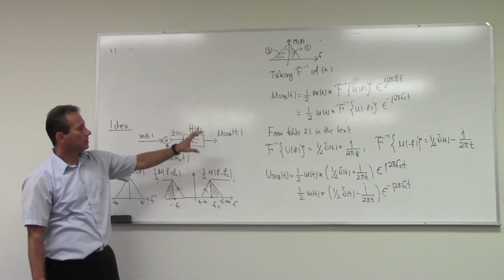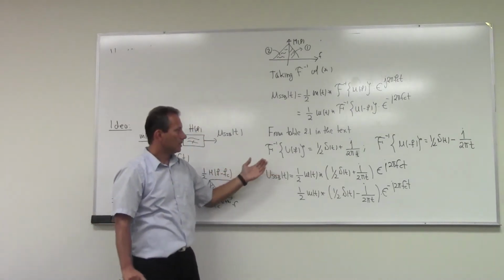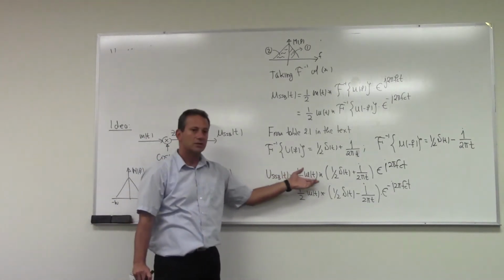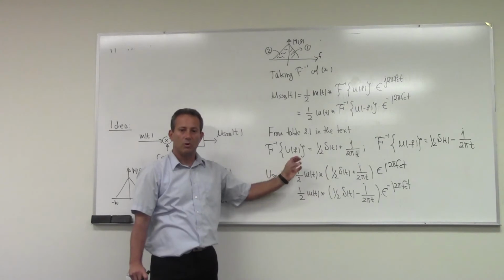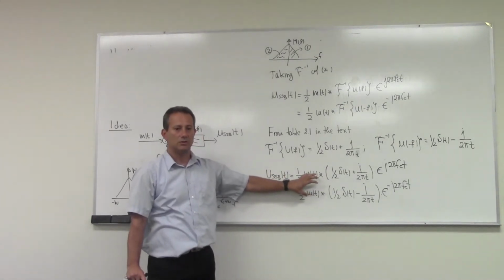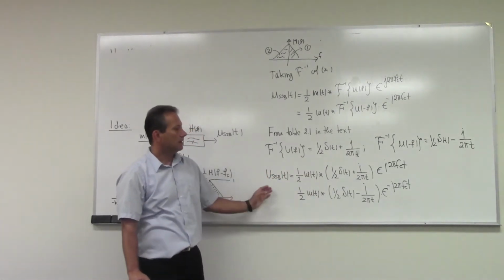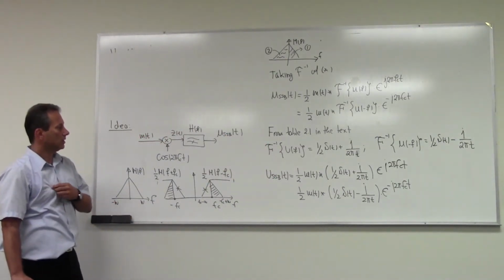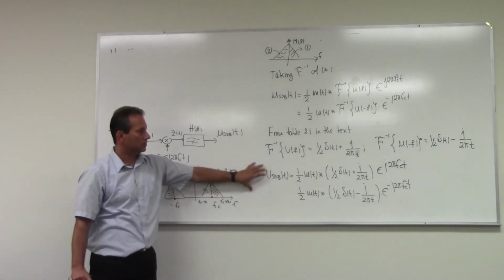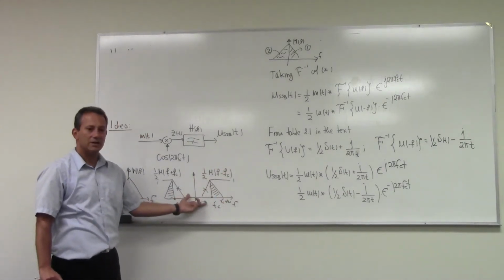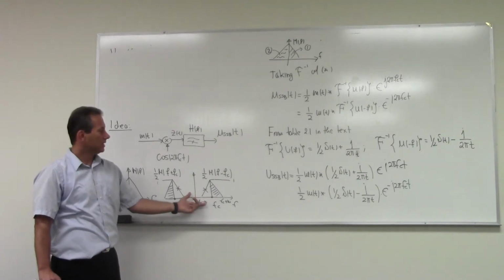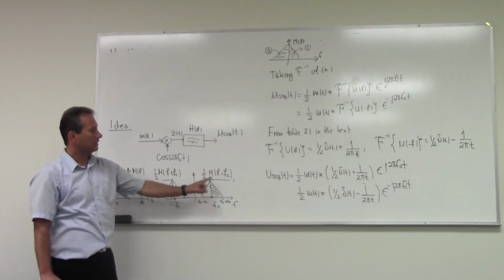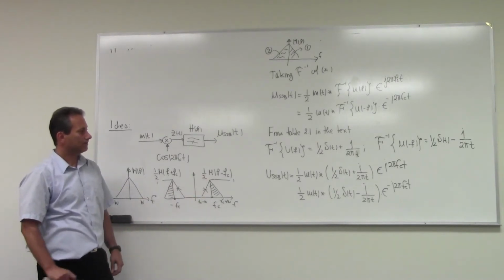Instead of filtering this at a high frequency, we're going to devise some filters at the baseband so that we do all the pre-processing where it's easier to process the signal, and then in the final step move the signal to the carrier frequency that we desire. That's the motive why we're trying to bring this to the baseband, because even though the idea is clear here at the carrier frequency, it is not practical. You cannot do this kind of filtering to get this kind of selectivity at a high frequency.